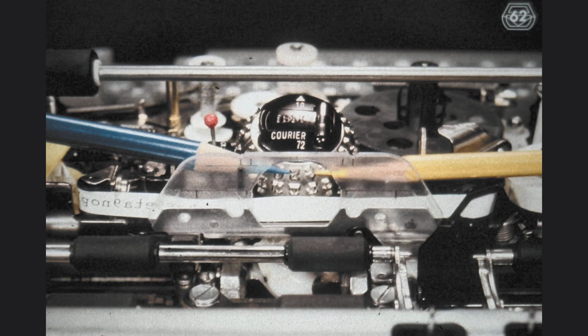Be sure to commit these definitions to memory, because we shall use them very often in this program. If we now wanted to print a $ sign instead of the Z, we would need rotation of the element in a clockwise direction. Rotation of the type element in a clockwise direction is accomplished by the action of a spring, called the rotate spring. Therefore, this rotation is negative.